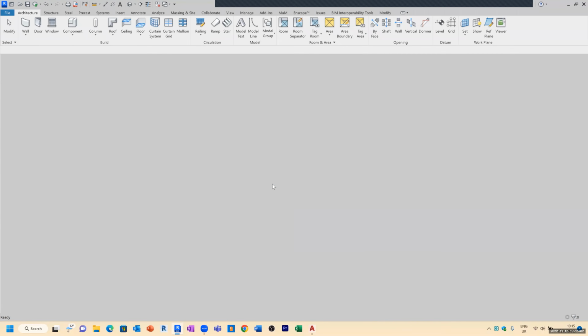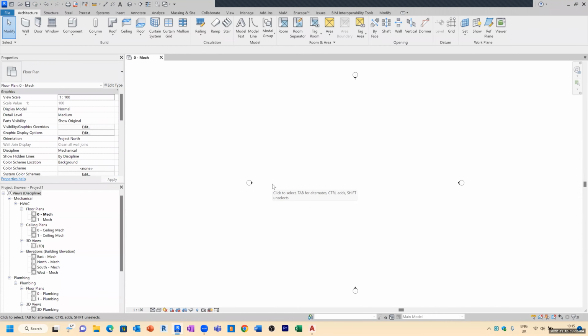And what I'm going to do, I'm going to use a completely blank Revit 2023 project template, and I'm going to create a project. I'm going to link in an architectural model, and then I'm going to create some MEP spaces, and then from there I'm going to create some design criteria, and then I'm going to create some supply and return ventilation systems. Okay, so this is all out of the box Revit. There's no pre-setup. I'm just using everything straight from Autodesk. You could actually have company standard families and templates, but this is all completely out of the box to show you how easy the software is to use and to start using.